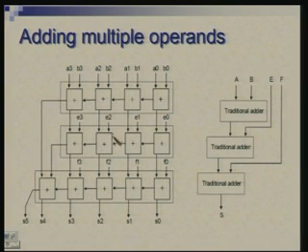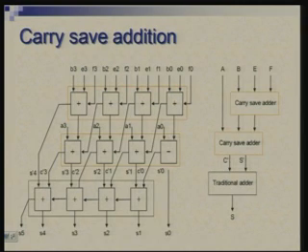This adder has to wait for some of this to come down. So, meanwhile, the carry of this also can be made available here, and we can also postpone this carry, let it go to next stage and so on. So, what we are doing here is that rather than making carries go to left, we make them go diagonally left and down, and therefore, the additional delay which might come because of leftward carry propagation will be cut down. So, here is a circuit which will do that.